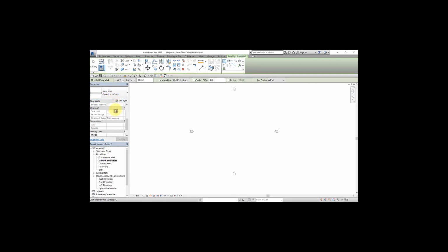This is a fundamental principle in Revit. Now, this is what you have to do. All the elements that you use in modeling, the best way to handle this is to duplicate and rename it so that you don't edit the system file. If I want a wall, I can personalize my wall. If I want to place my windows, I have to personalize my windows so that it becomes easy to identify them when you're doing your shadows. So now let's edit our wall.